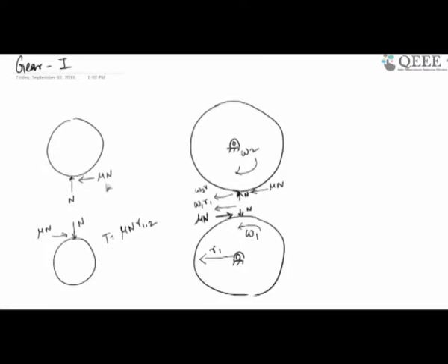This is what I said, and the point is that this normal force is going to eventually get transmitted to the shaft also, because the disc which is experiencing that force n is going to transmit that force back to the shaft. This is the free body diagram of the disc, not of the shaft.